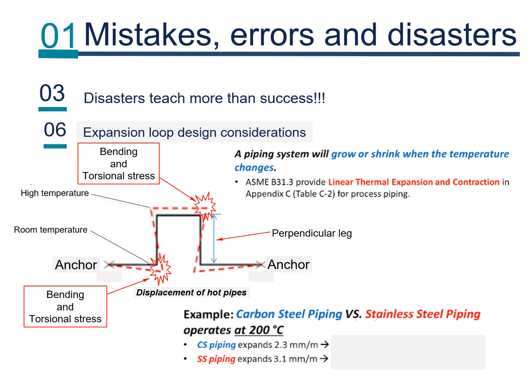Thermal displacements which need to be compensated can be evaluated as shown, so it is easy to see that for long stretches of pipe, even at low temperatures, the required displacements for compensation can still be quite large. When the proposed design is completed, it is sent to stress for accurate calculation of anchor loads and accurate evaluation of stresses in the piping, then transmitted to structural for structural analysis.